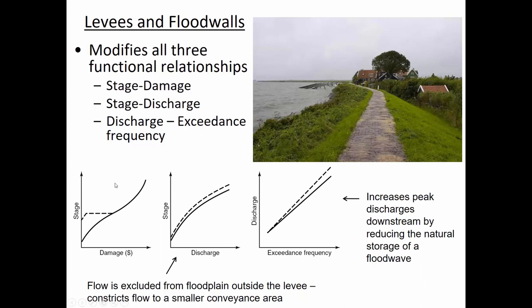So the levee does one good thing and two bad things. Now the net effect is positive because hopefully we're only having a small increase in the discharge, only a small increase in the stage, and you're protecting all of the area surrounding the levee.